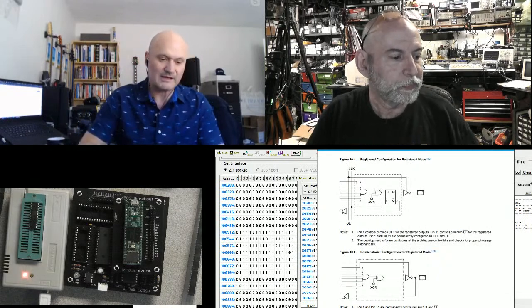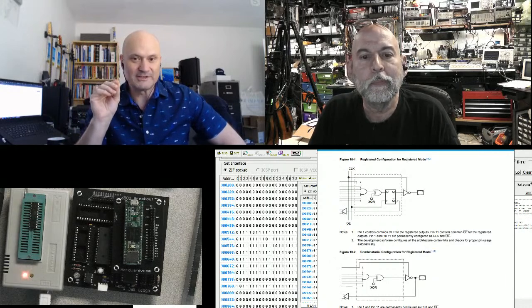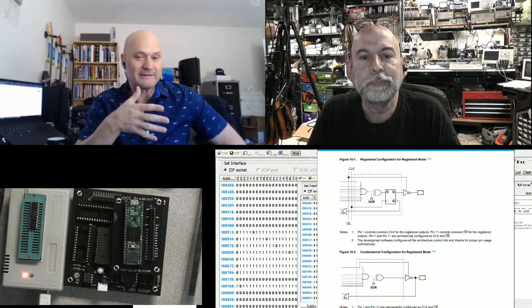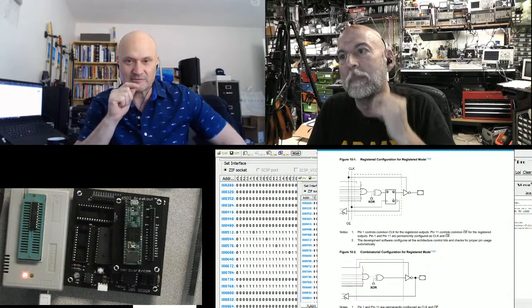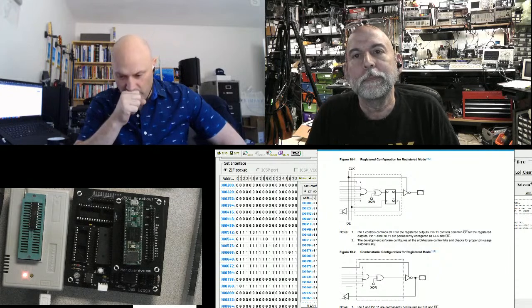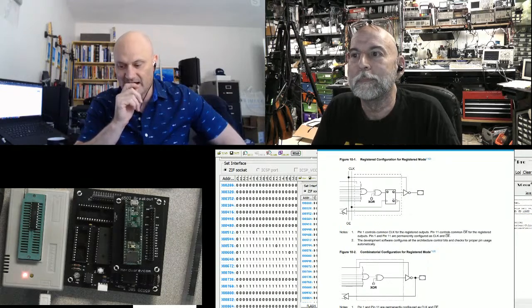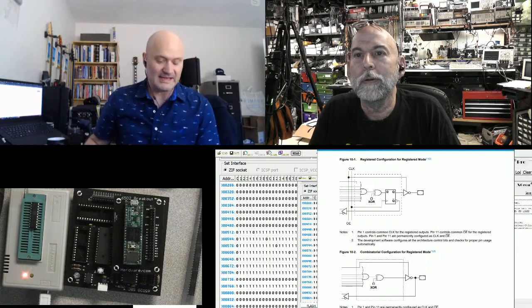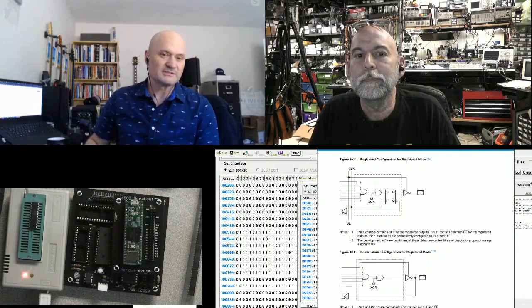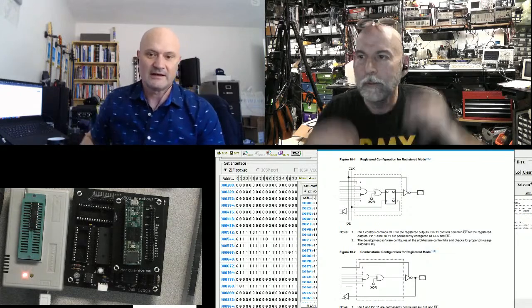So anyway, I finally got to almost completion, and this week I started routing the board since our last Friday, and within a few hours I had it almost completely routed. I was blown away with how good the routing tools are already in Fusion. So I had a really easy time doing that. It's going to be a 4-layer board just because I want good signal integrity. So I've got plane layers on the inner 2 layers. And then,